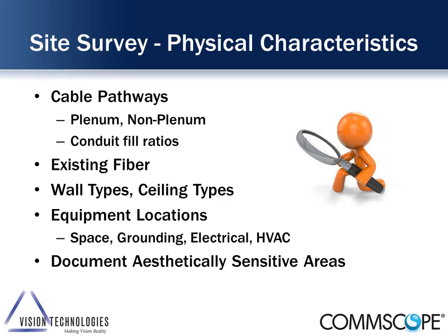And so there are various different concerns when you're drilling through floors in buildings. There are a lot of different things: you may have to take x-rays, and you may only be able to do that at night. And so understanding whether we'd have to create vertical pathways is important. Also with horizontal pathways, are we going to be going through drywall? Are we going to be going through concrete block or maybe firewalls? And repairing the pathway or fire stopping the pathway is very important to understand as part of the entire process.